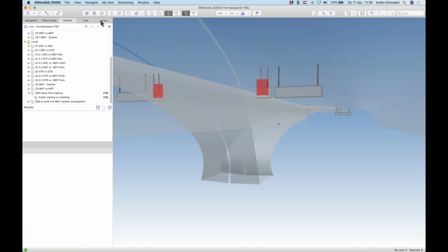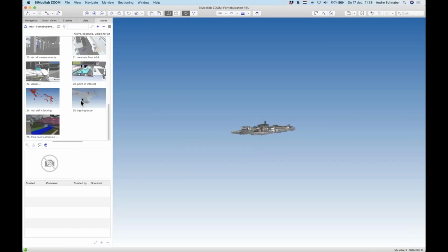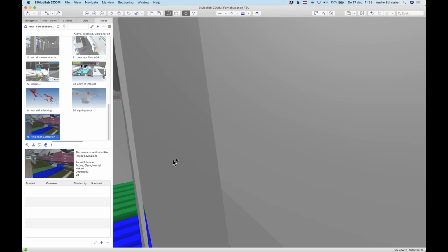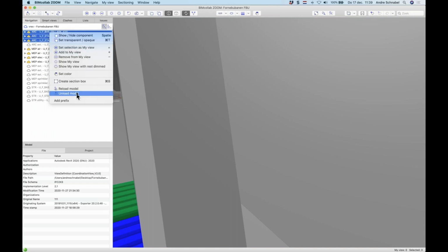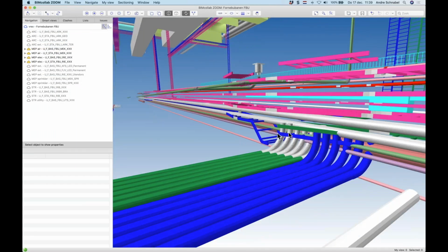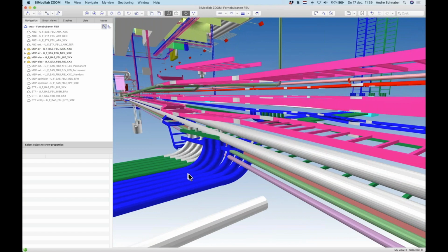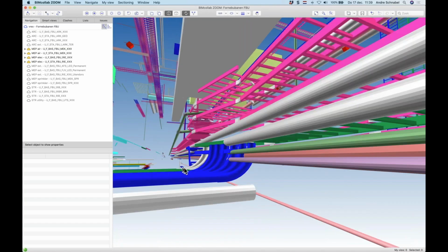And of course, I can go back and synchronize in BIMCollab Zoom to get the issues again here into my system. I will put down my architectural models to have a better view on the focus here, and to understand the models, having the preset for my clash detection.